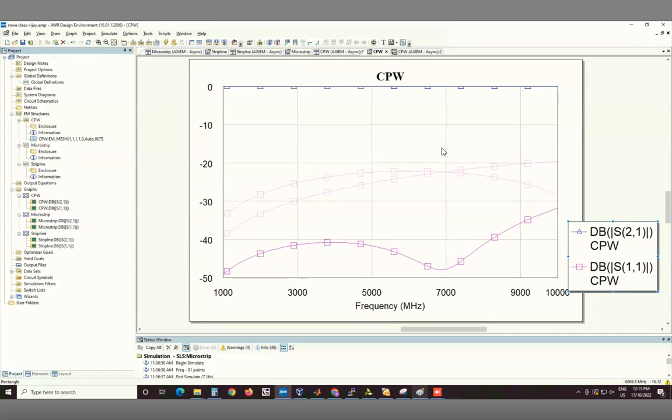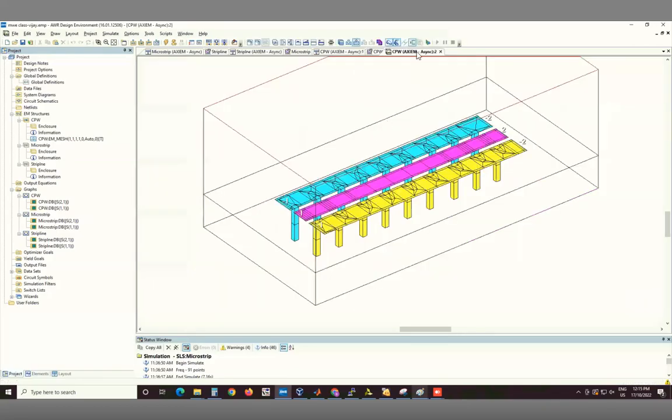So this is very crucial. I didn't bring it, but you saw in those transmission lines there were these holes all along the length of the transmission line. Those holes are exactly these connections, and they are made through an electroplating process. There is metal on the bottom and metal on the top. We drill holes, and then a special chemical is coated through that hole. Then you electroplate copper, and it grows from one side to the other. That's how you create the via. This kind of technique works for circuit boards, and we have a special machine to do that.